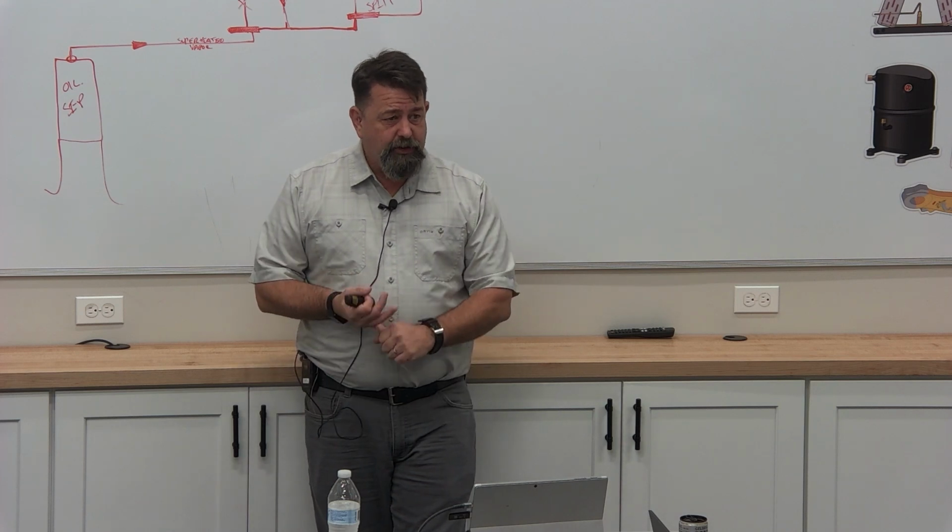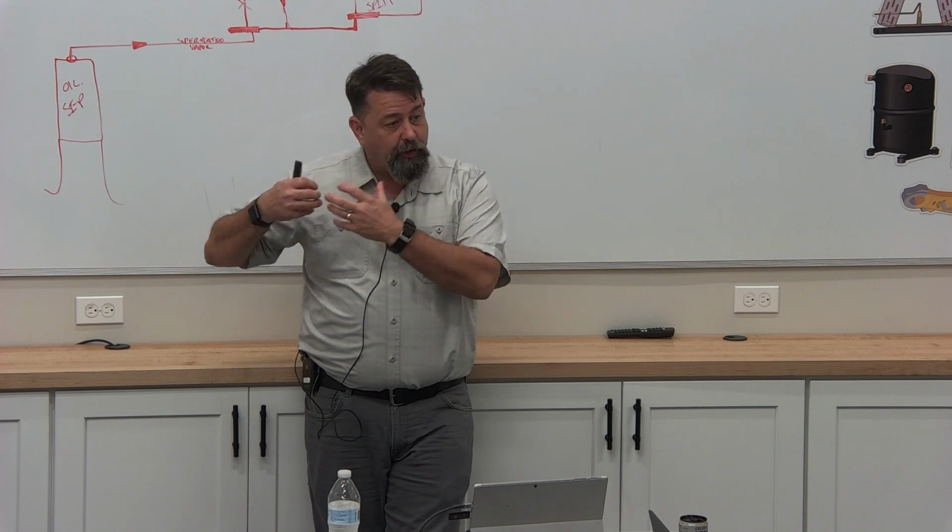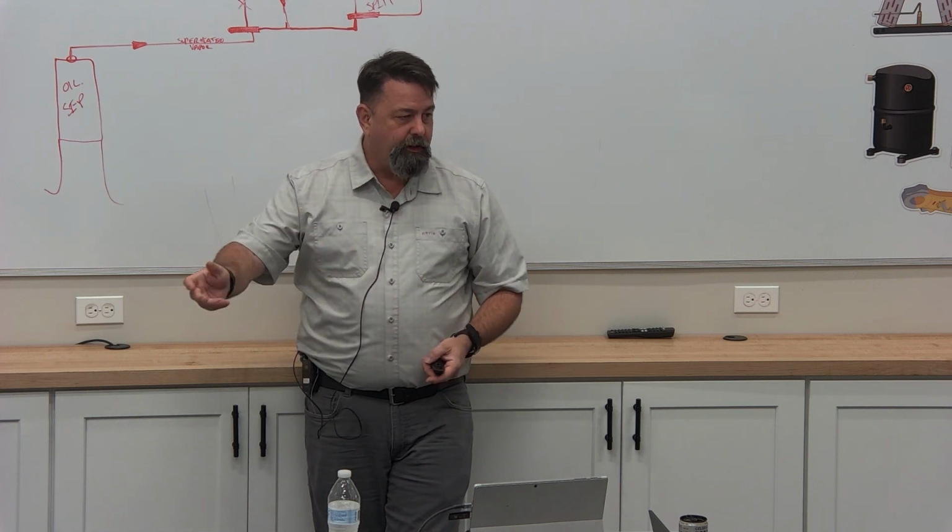But if I'm adding digital unloaders, now we're doing some good stuff. Now we're doing something. Because now I can even cycle these compressors on and off. I'm not actually turning on and off compressors. I'm just loading and unloading.